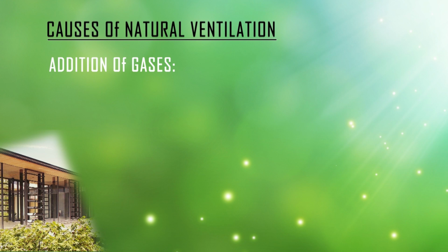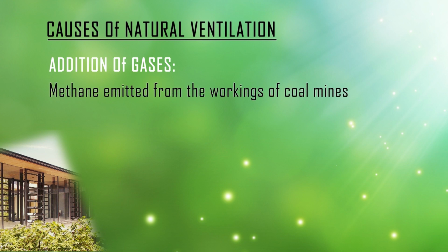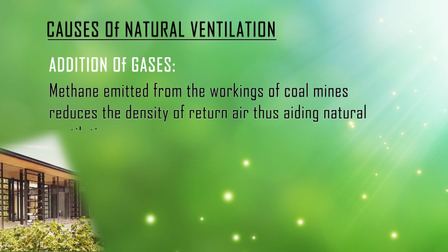Addition of gases. Some light gases, just like methane, which are emitted from underground workings in coal mines, when mixed with air reduce the density of the return air. The return air density becomes less, so it becomes lighter, and lighter air moves up and natural ventilation comes into role.